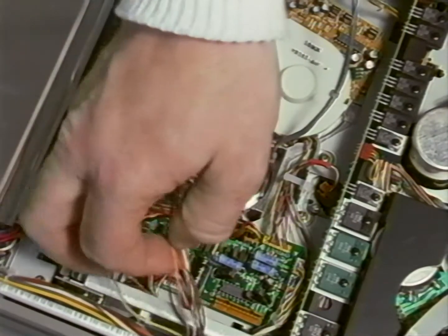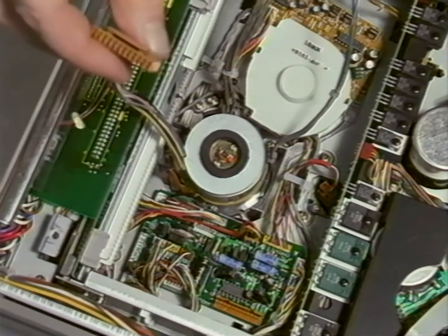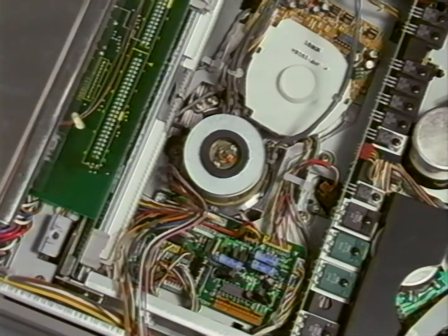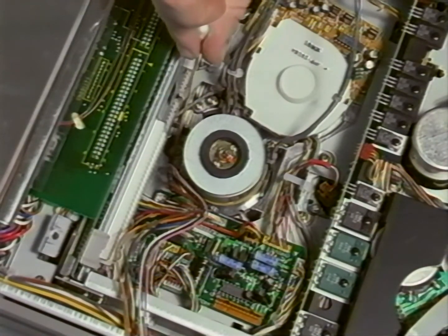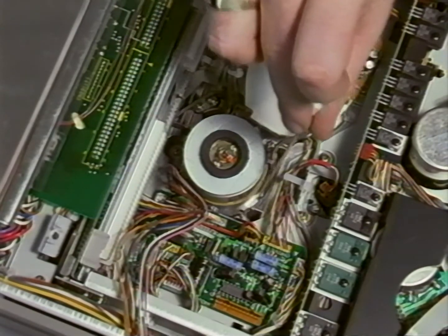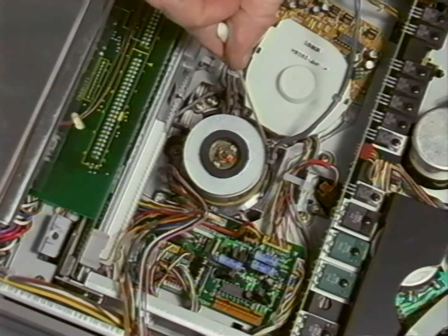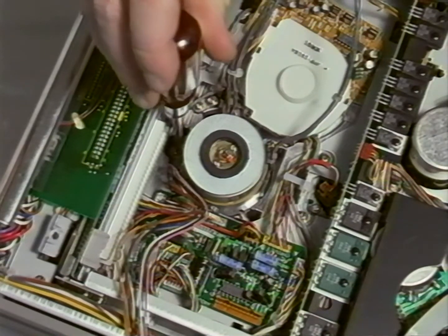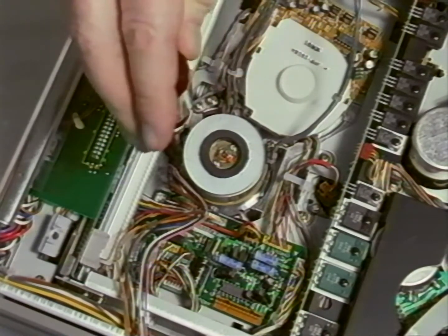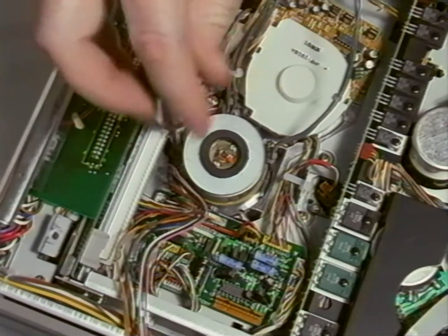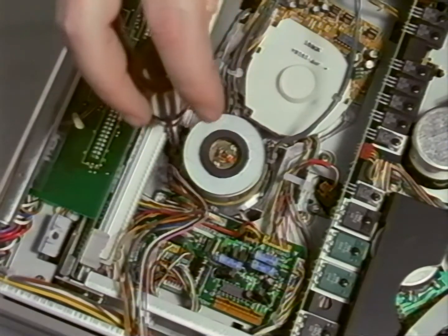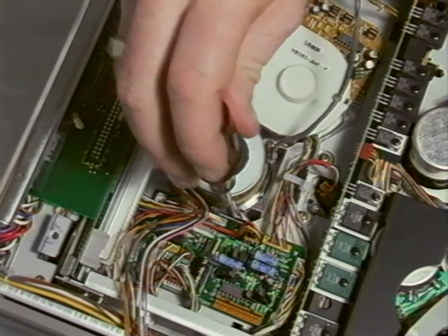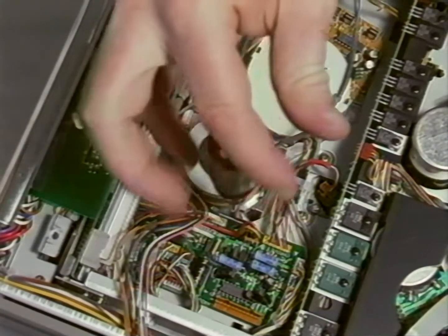At this point, all harnesses from the drum assembly have been freed and the drum can be removed. 3 screws can now be removed from the underside of the chassis. The bottom panel and 2 SY boards have already been removed. It is best to put the unit on its side and remove the screws while holding on to the drum from the top side. This will prevent the drum from falling out or prevent stripping the screws.